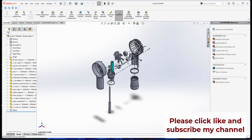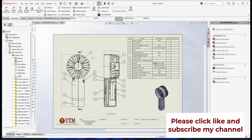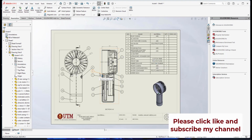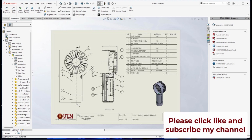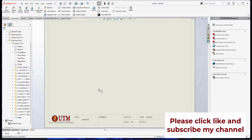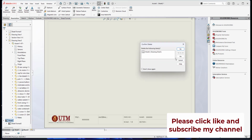Since I have done the exploded line sketch for the components, now I will go back to the drawing, right? If you look at the drawing, I already did the assembly drawing. At the bottom left, we have sheet 1. By the way, if you click add sheet, I can add another sheet, but if I add a new blank sheet, I don't have the bill of material. So I need to delete it. I don't want to simply add a new sheet like this.